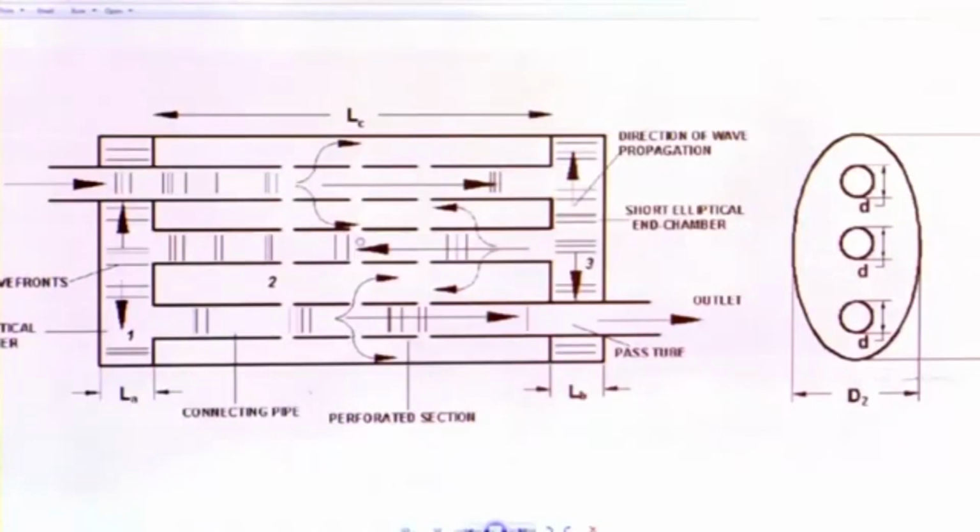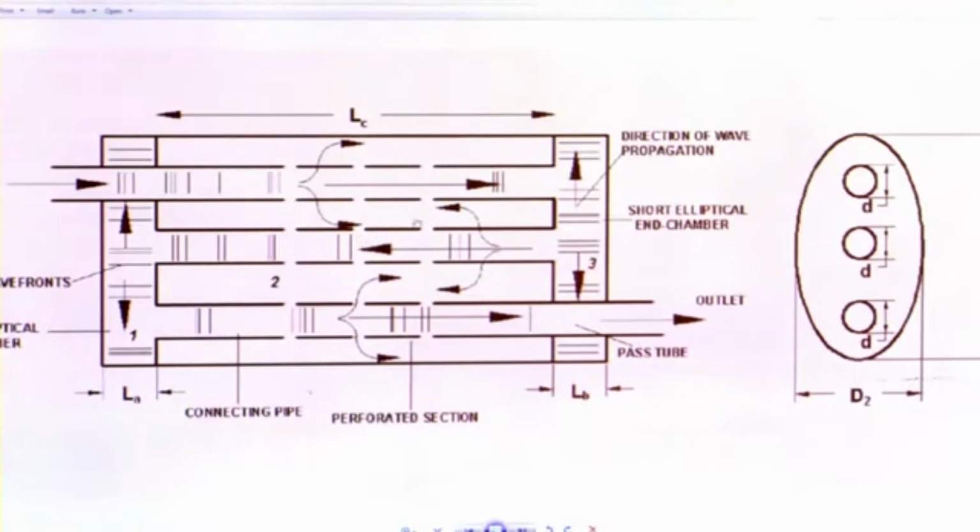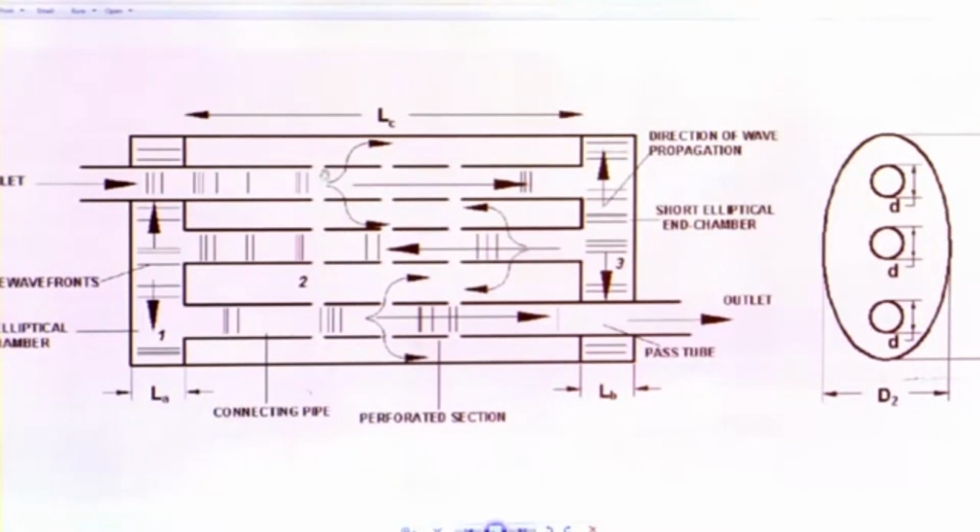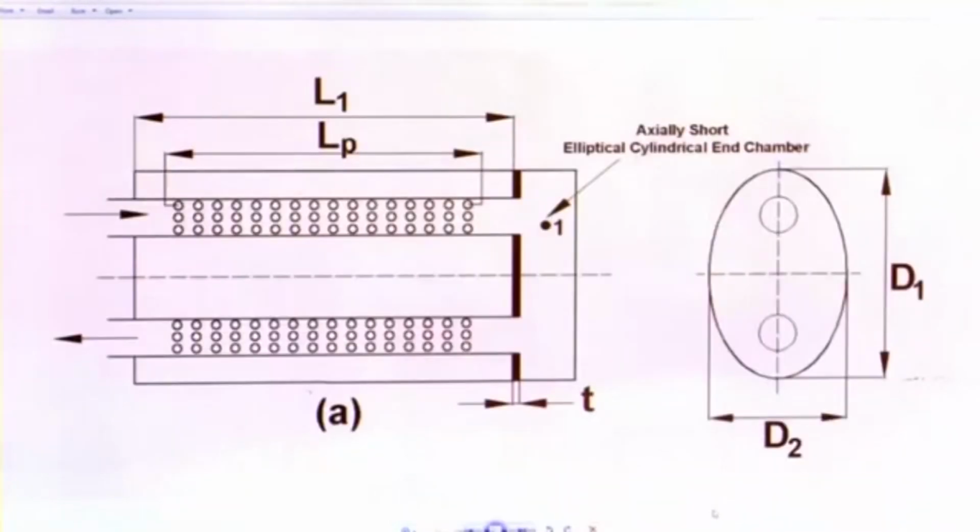Look at then this figure. Well, this is something also known as a multi-pass perforated duct silencer. Basically you have an outer shell. You can also have a look at perhaps this figure. So, what it does is basically it shows you there are two configurations. The overall shell is elliptical in shape, and you have two perforated ducts, also in general known as multi-pass perforated silencers.